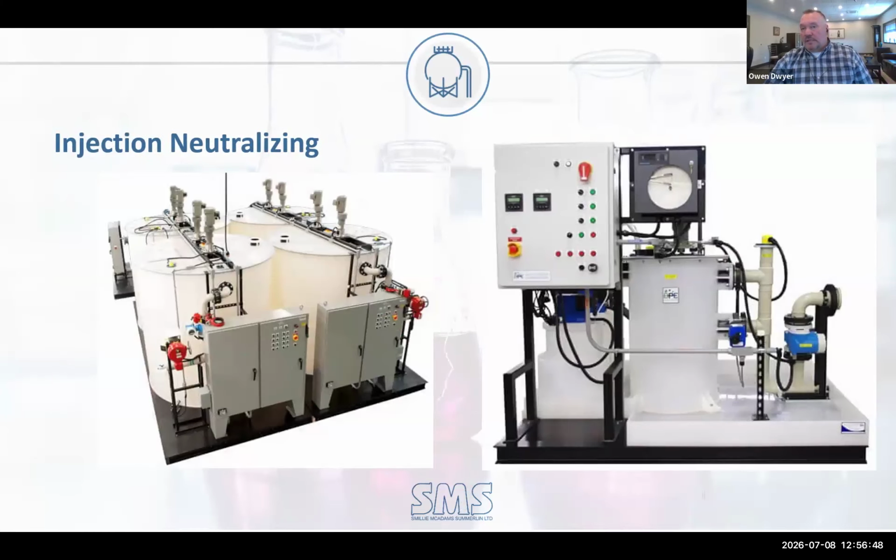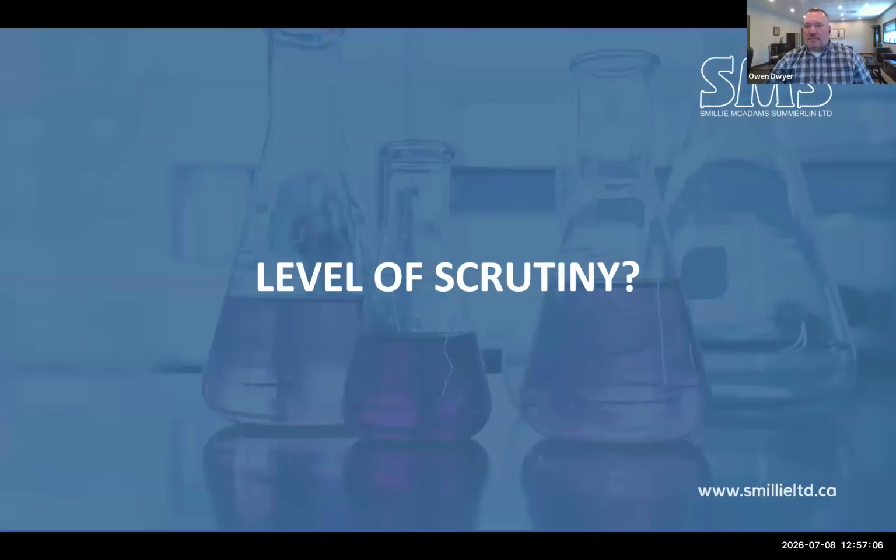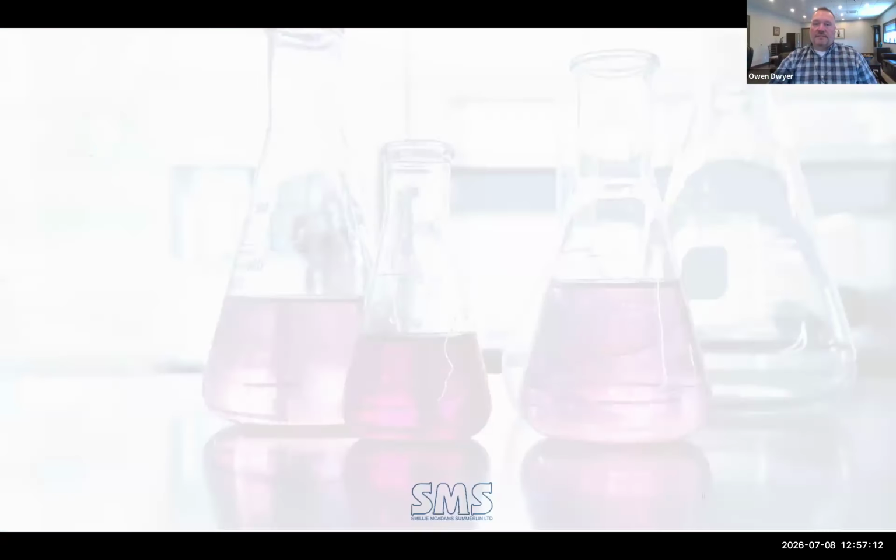N+1 redundancy. On the left-hand side, if you have this massive skid system, you can see that each tank has two agitators. There's multiple pumps. So if any component in system A goes down, there's some control logic built in that switches it over to system B, etc. But in the end, they're all the same as far as the components: you have a reagent, you have a pump, you have your pH monitoring, etc.